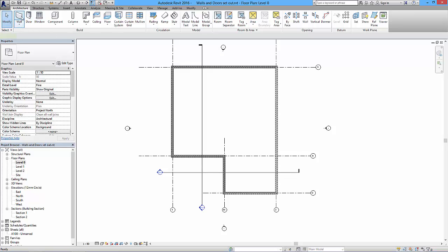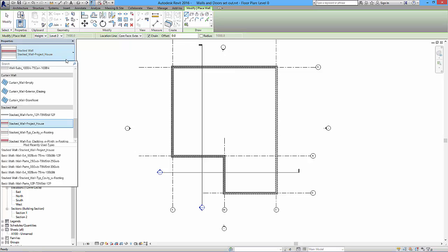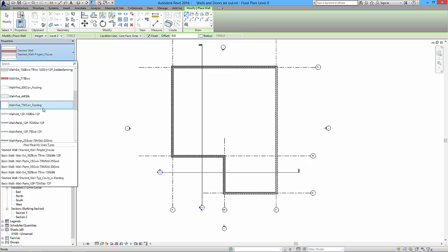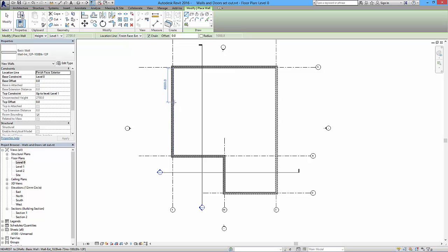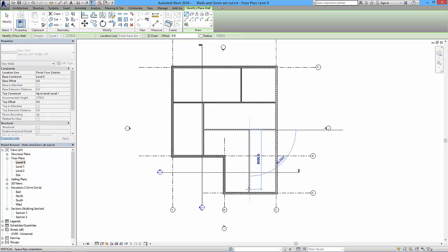And we'll use the wall tool, and we can use basic walls. Now take your pick. You can either go for internal block with plasterboard, so we'll use some of those on the ground floor, and I'll just put a couple in across there, hit escape once, and then down to that bit, hit escape. I'll just come down. I've no idea whether these are the right size or not for anything. I've no idea about the layout, but we'll put some of these sorts of spaces in.